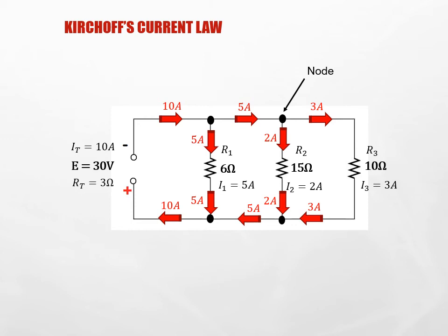Whatever the current is that's entering the circuit must also be the current that is leaving the circuit. The circuit must be balanced, and it will be, it should be, it must be. This is the basics of nodal analysis, and using Kirchhoff's current law to figure out what current will be flowing in which conductor.